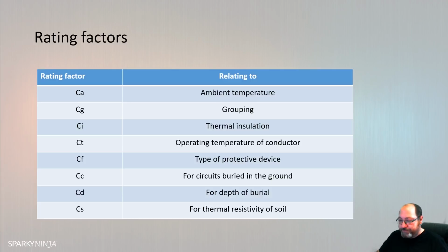Also, in 433, there was mention of when we're burying it in a duct, the temperature would be 20 degrees. So again, we apply a factor of 0.9. Similarly, we may consider the depth of burial and the thermal resistivity of the soil. All of these things are factors that can affect cables under load. And so we'll look at those now.